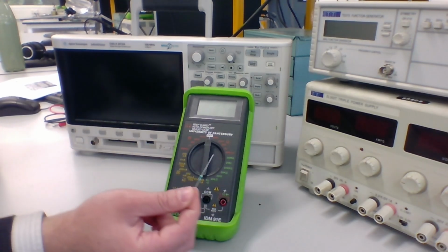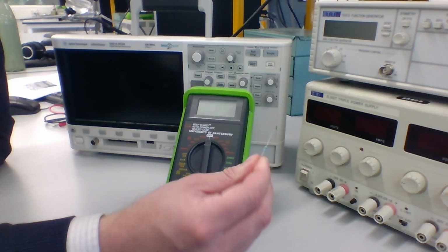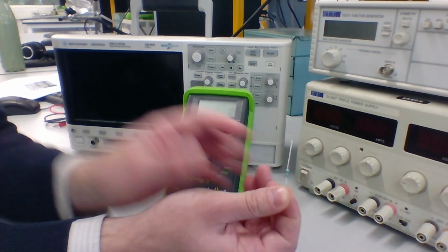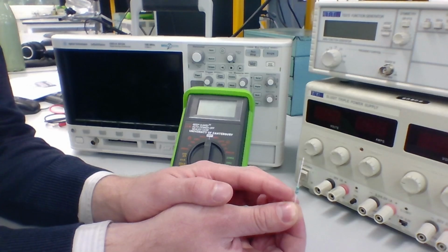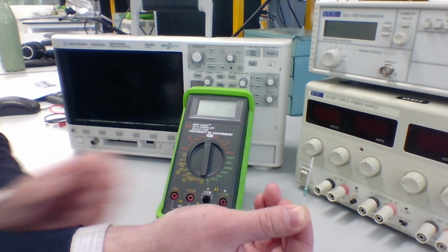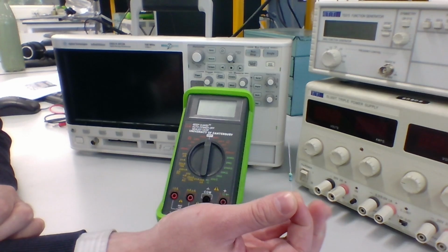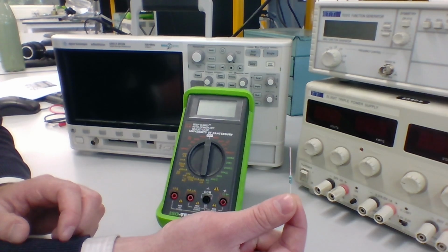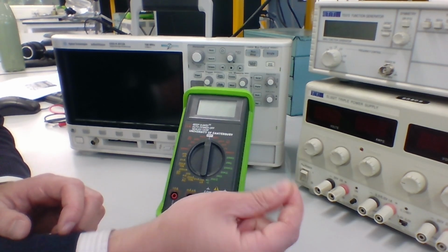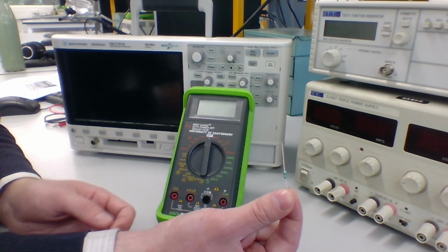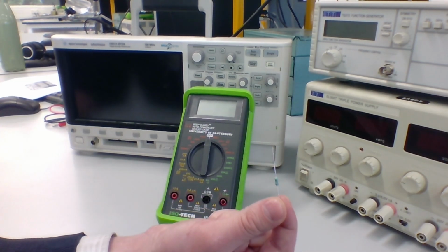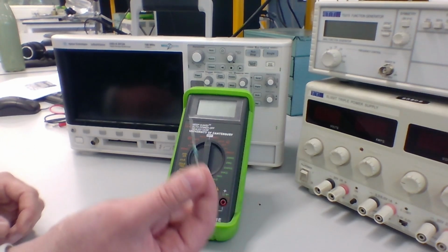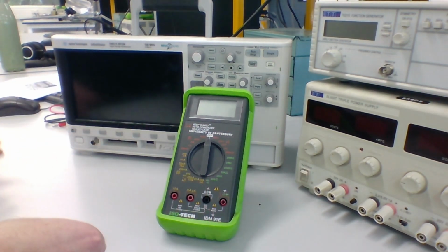You can then identify the resistance of this resistor in one of two ways. One is by looking at the colored bands on the resistor. They encode the resistance and tolerance of the resistor, and you can use a color chart such as the one in the red folders, or there are many available online, to decipher or decode these bands and determine what the resistance of this resistor is. The second way you can do it is by using a multimeter, such as this one here.